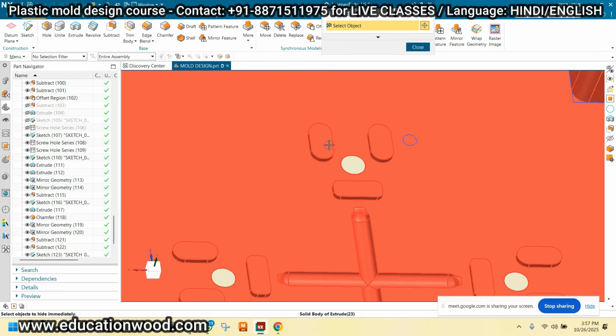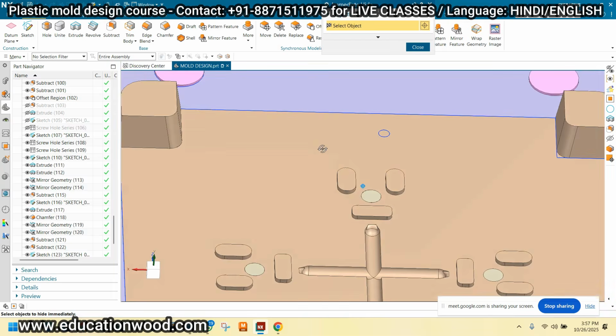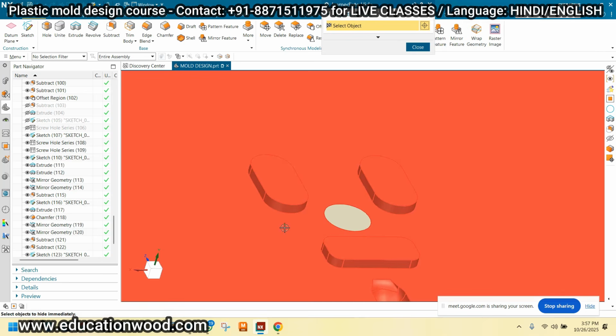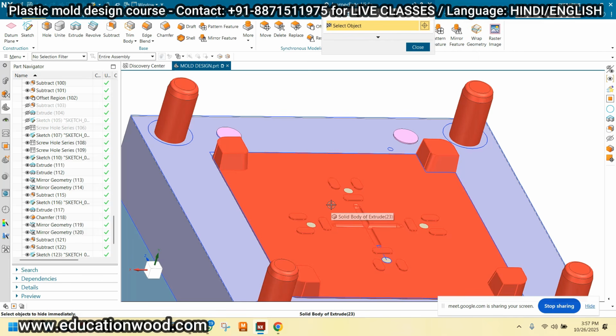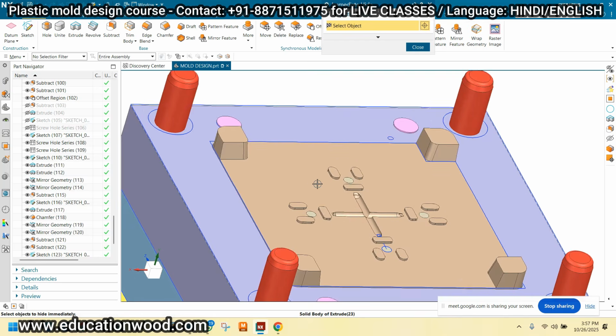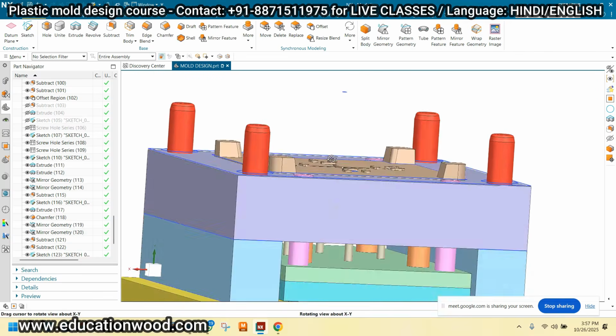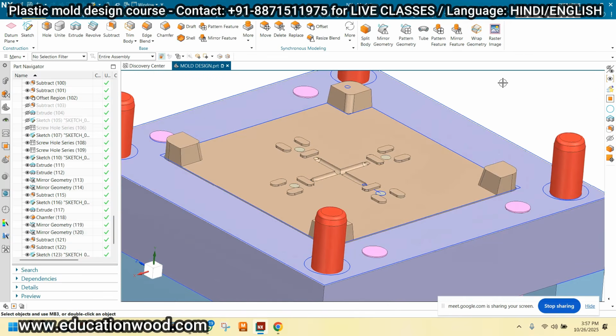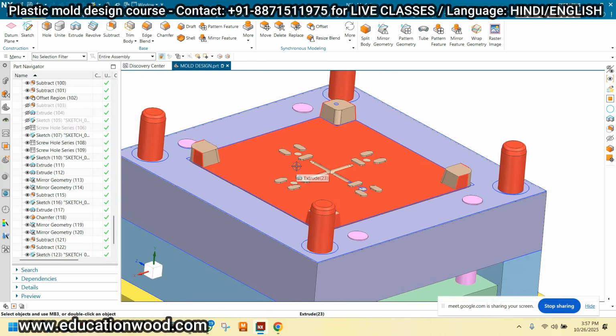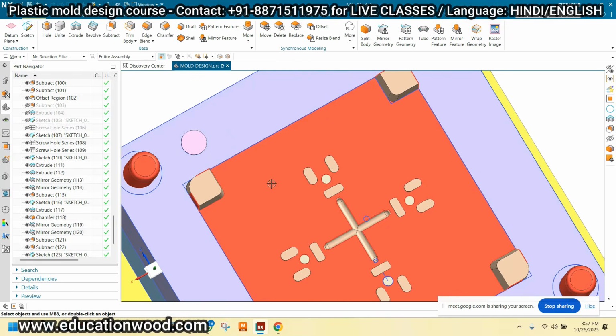Something happened, for example, something makes an accident with the feature of the core and the cavity. So basically you have to take the machining also, you have to prepare the machining again, right, on the core or the cavity plate. So basically you need some reference, right? So that's why basically we have to prepare the reference hole.